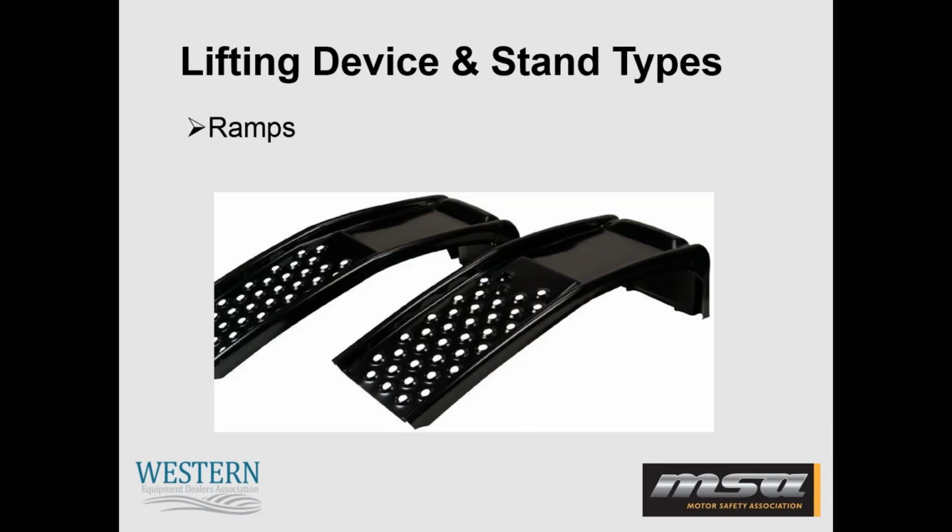Talk a little bit about ramps. They are a safe alternative to jacks and jack stands because they provide a large solid point of contact that's unlikely to fail. However, when you're using ramps, just be aware of the maximum capacity and the weight of the item on the ramps, and always be sure to set your emergency brake and chock the wheels when the equipment is on the ramps.